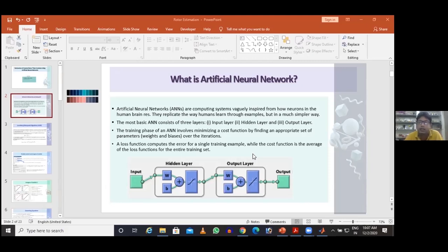low voltage till 600 volt or 650 volt. So there, microcontroller, the communication, optical communication. Then when you are firing the IGBT or semiconductor switch, there will be some conduction and switching losses that is to be evacuated. So to evacuate that, you have to design the heat sink. Then what kind of cooling is required? If the natural cooling is not sufficient to evacuate the heat, then you have to introduce the forced cooling. So these are the multidisciplinary aspects involved in motor control.